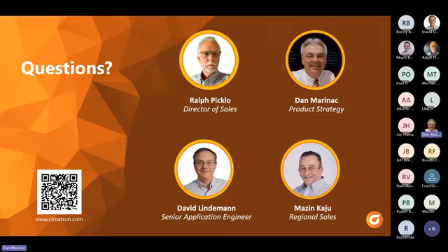Third question, why do we have to run a formability simulation first before we get the spring back analysis? Again, maybe I'll jump on that one because it's part of the theory. When we run a formability analysis first, we're understanding the strains that the punch and the die and all the rest of the mechanisms like binders and blank holders and pressure pads put into the part.